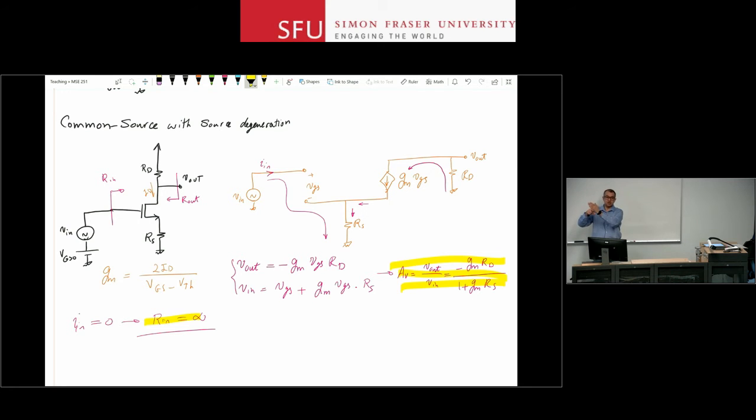If you use a BJT, you will draw some current. You will load the circuit. With a MOSFET, yes, you may not get as much gain, but the probe is not going to affect your circuit. Same thing with an oscilloscope probe. There are a lot of applications like that where this infinite input resistance is very valuable, maybe more than the gain.